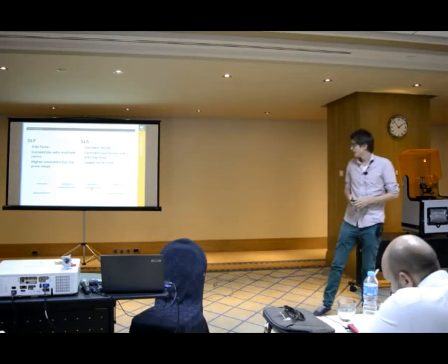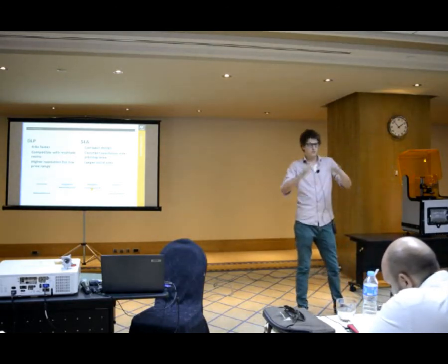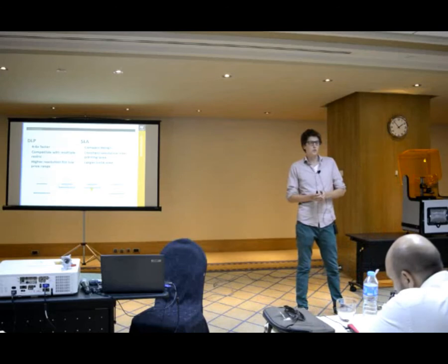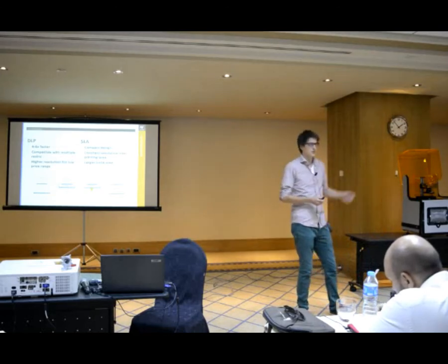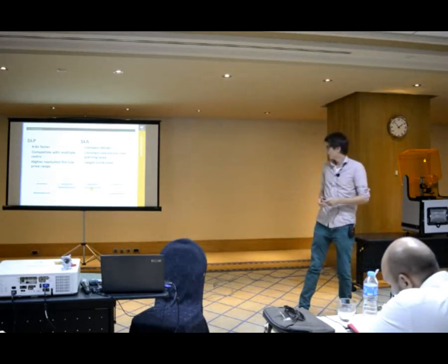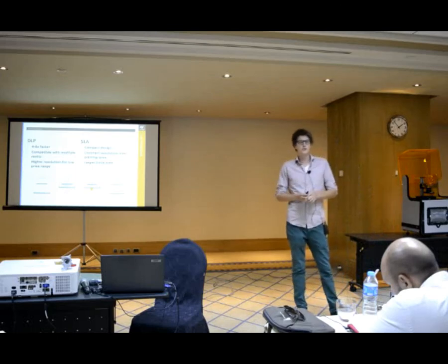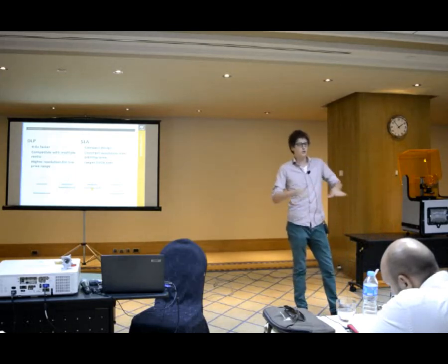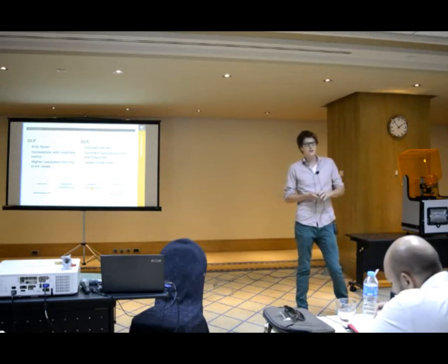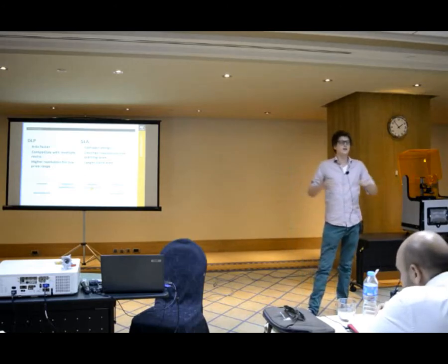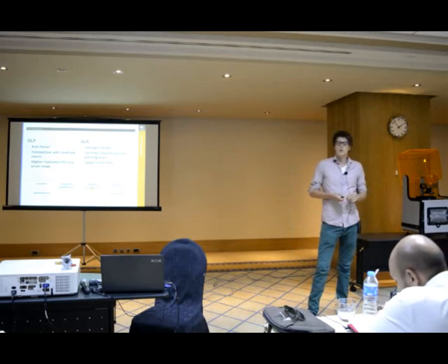On the other hand, the design of the SLA printer itself is more compact than, for instance, the DLP you see here. The resolution of the SLA is constant over the entire surface, and the build area is bigger for an SLA than for a DLP.